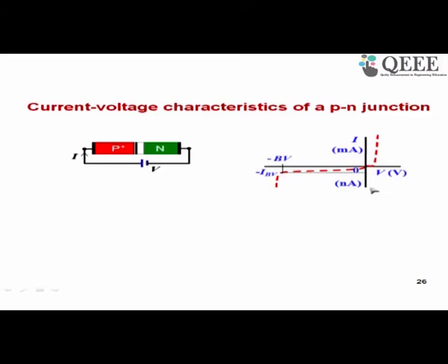Often what happens is students remember the shape of the curve, but they do not remember the orders of magnitudes of quantities. Okay, as we will see, the same curve will appear of a different shape if you change the scales. Now before we come to that, let us see other features of this curve. So beyond some reverse voltage, you have breakdown in which range the current increases rapidly, even if you increase the voltage by a small amount.